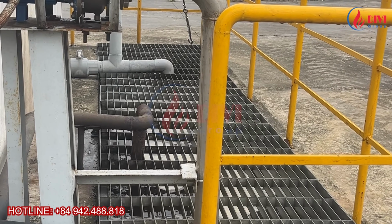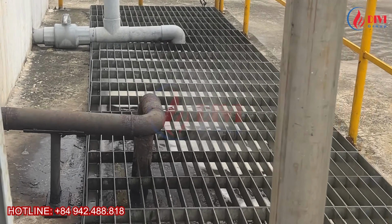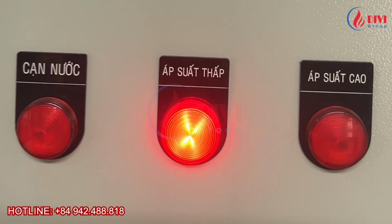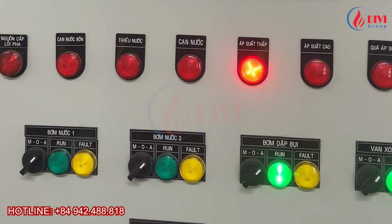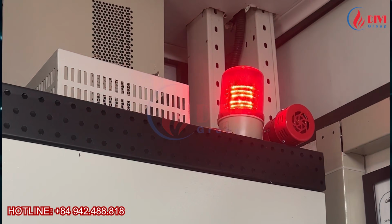Safety precautions. If the discharge outlet leads to a drain or open area, always warn nearby personnel before blowdown. Do not perform blowdown when the system is under high steam demand, to avoid a sudden pressure drop. Do not perform blowdown when the water level is low. The safest condition is to perform blowdown at a high water level.